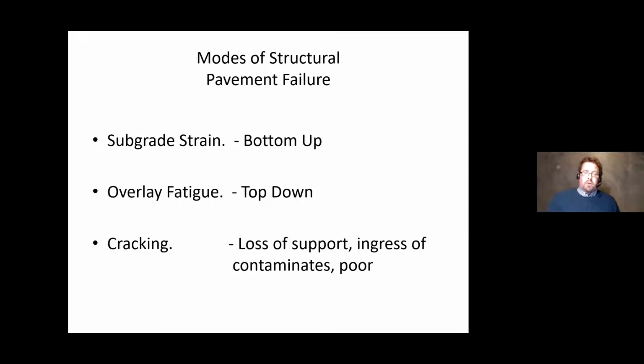So in terms of structural failure, you'll have subgrade strain, effectively it's bottom up, which means your subgrade is starting to suffer, your subgrade is having an effect on the pavement. So you're cracking, or you'll have degraded subgrade, degraded granular layers, and you'll start ending up seeing rutting and cracking and settlement.